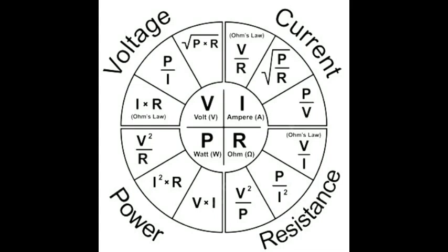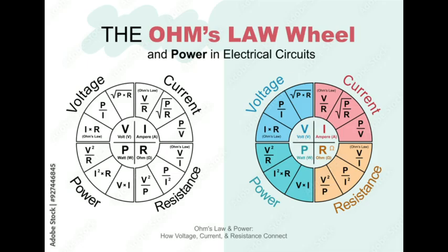My missing resistor would be 1 divided by 0.2. It would be 5 ohms. So we would enter right here 5 ohms of resistance. And this is how we use our formula number 4.